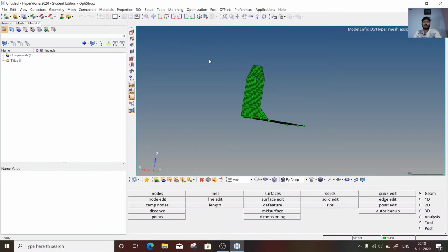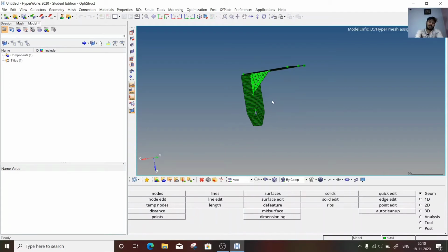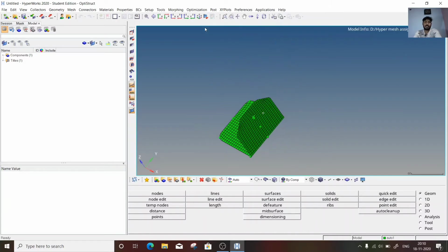Okay. Also, at any time if you want to see the reverse view, you can press Ctrl and the Page Up key on your keyboard. That will reverse your model. If you want to know which tool does this, at the top you can see here, reverse view. Hope you are watching where I am locating. You can click here, it will reverse your model.